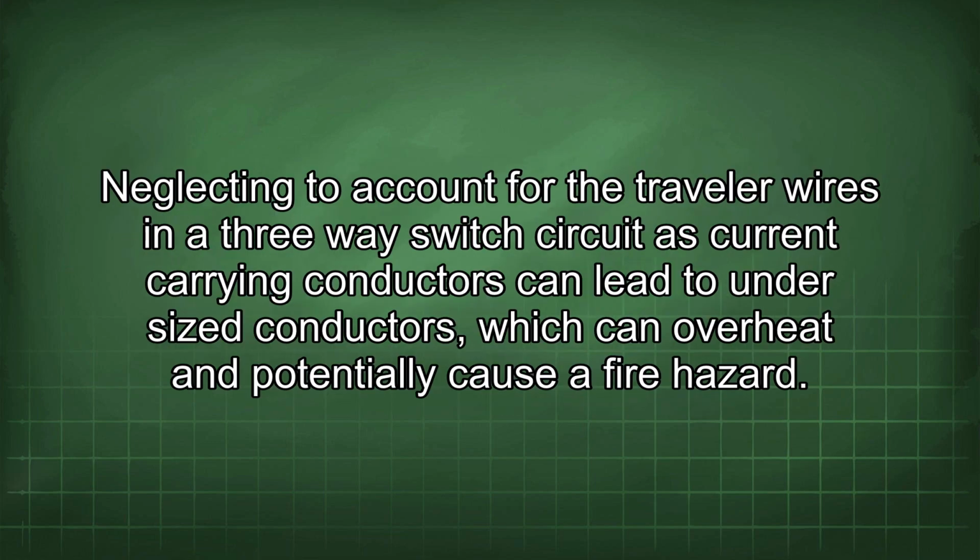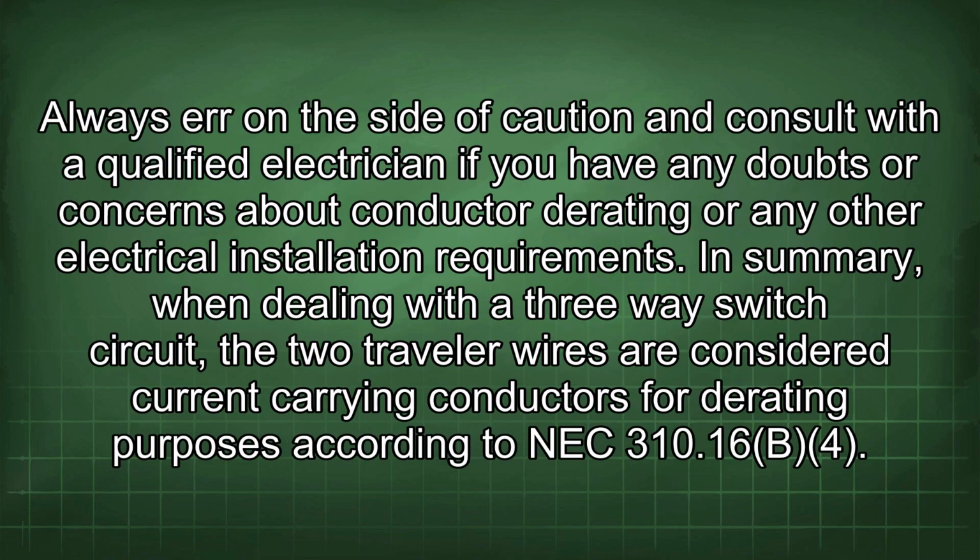Neglecting to account for the traveler wires in a three-way switch circuit as current-carrying conductors can lead to undersized conductors, which can overheat and potentially cause a fire hazard. Always err on the side of caution and consult with a qualified electrician if you have any doubts or concerns about conductor derating or any other electrical installation requirements.